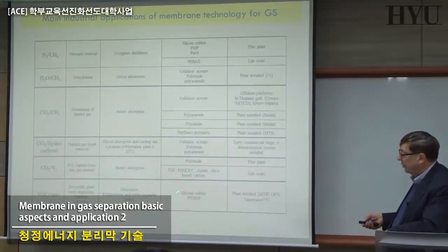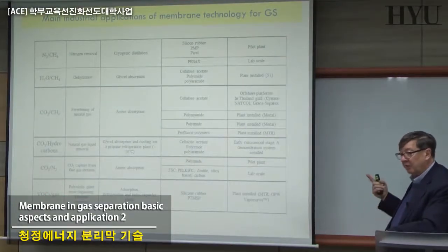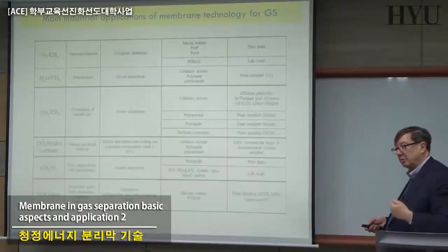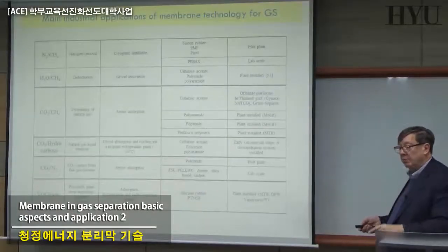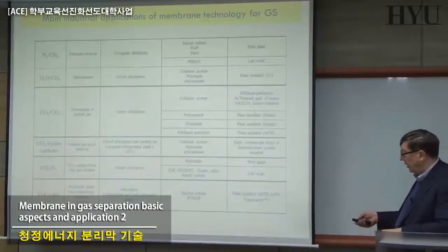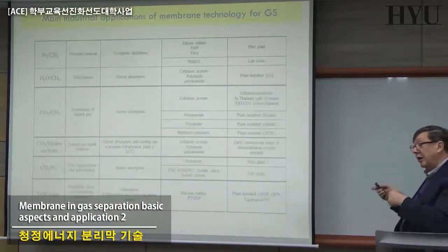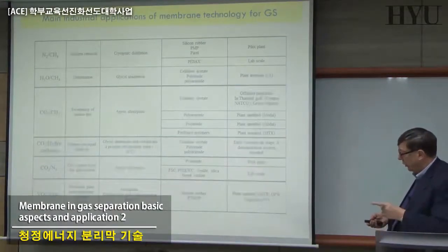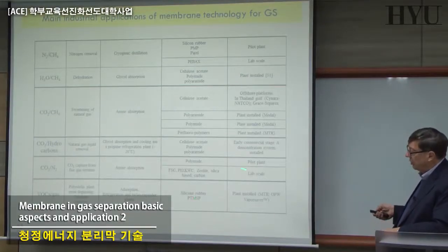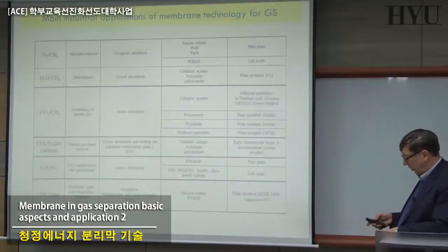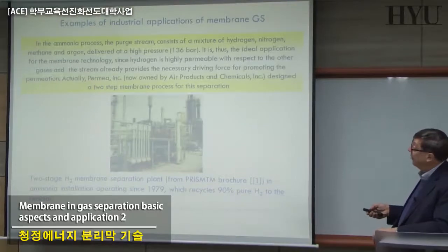And today you can use these PTM membranes in which the VOC are very soluble and they go easily across, so you can recover these monomers and utilize them in the process itself. And these are becoming very, very standard now, are relatively expensive. You must be aware, and you have to take care of the health of the people, but also the health of your company, because part of the costs you can recover easily in reusing the VOC in the process itself. And some of these plants exist.